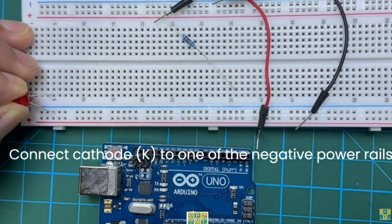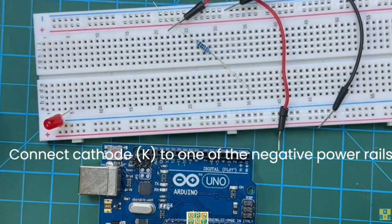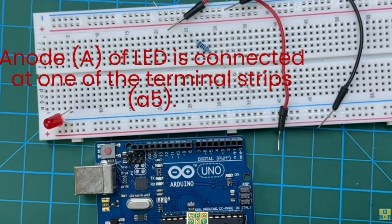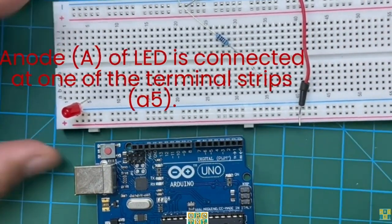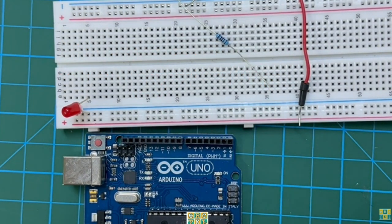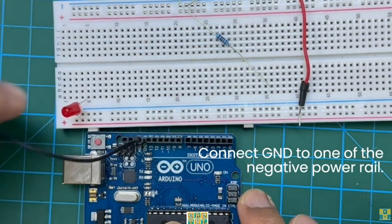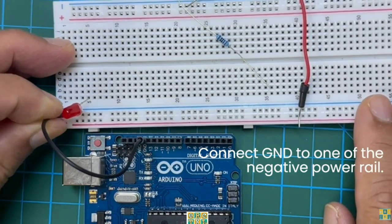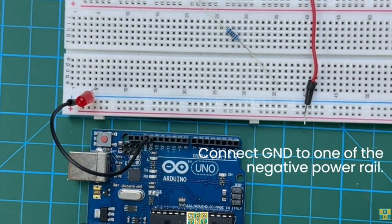Now we connect the cathode to one of the negative power rails, and then the anode we connect on one of the points here. I connected the cathode to the negative power rails, and I connected the anode to letter A5. I hope it's clear. Is it clear? I put it on A5, all right? Do you understand the circuit? Then we connect the ground, GND, and we will connect the ground to your negative, or to the cathode of your LED.